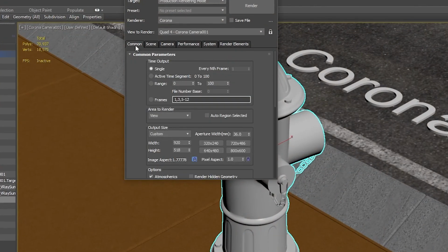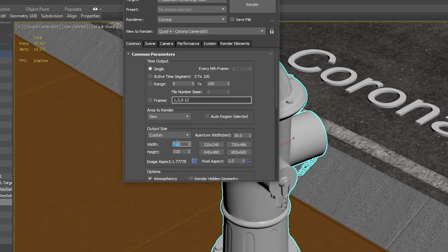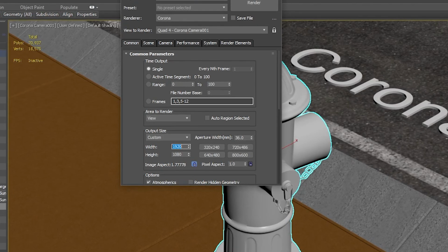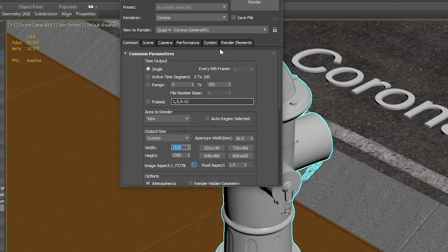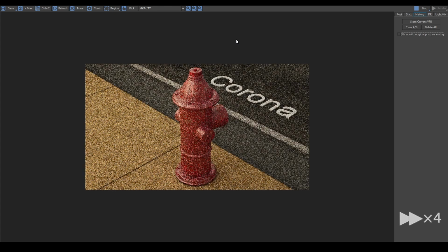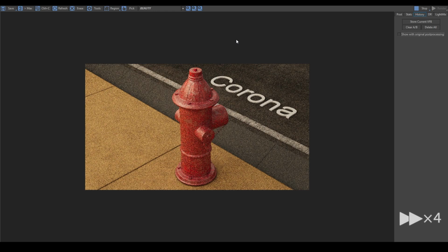Now that I've reached the final result, let's move on to the final render. I'll increase the quality to Full HD. Switching to the camera and starting the render. I'll speed up the video to make the process faster. A quick note about Vray dirt. It differs from Corona Ambient, and it might not look exactly like this render, but you can still create dirt effects with it in a different way.